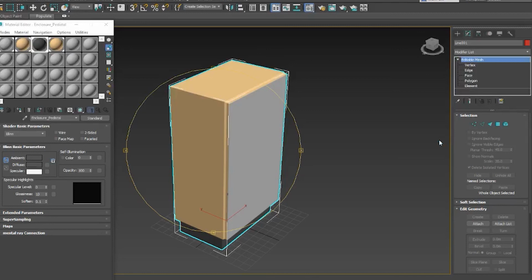If you saw them at all, they'd probably be distorted or stretched. Probably completely obliterated. Also, lighting wouldn't work right. Your models need to have UVW maps on them for Unity to calculate the baked lighting properly.